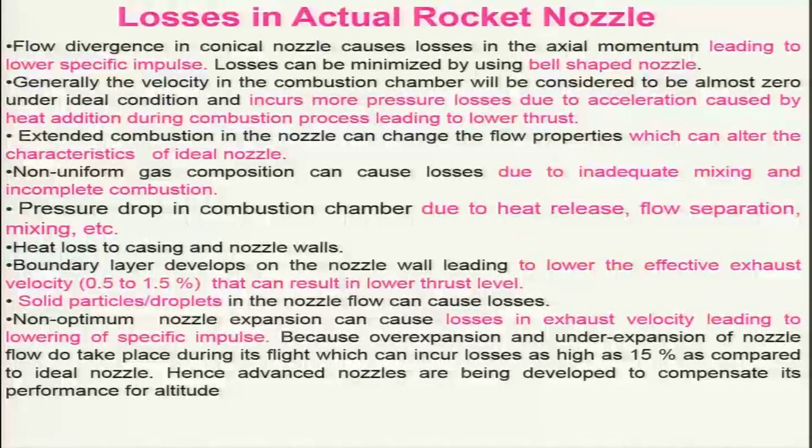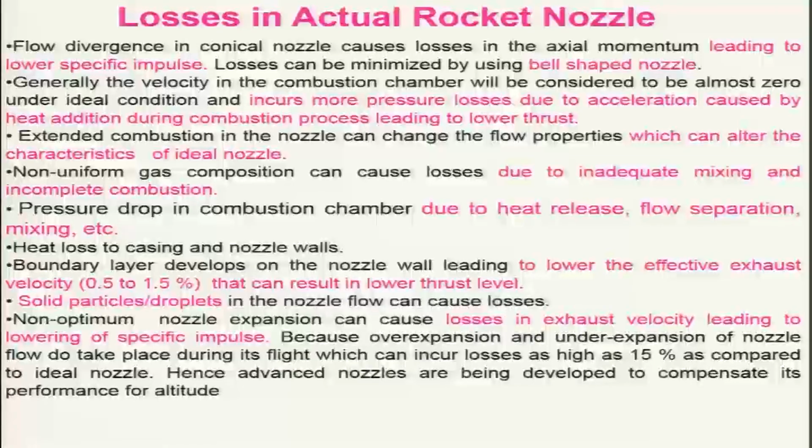As I told you, a particular nozzle will be designed for a particular altitude, however one has to travel through certain altitudes. So, the nozzle is subjected to over expansion and under expansion during its flight, which will incur losses as high as 15% compared to the ideal nozzle. Hence, advanced nozzles are being developed to compensate its performance for altitude, which we will discuss a little bit in today's lecture.